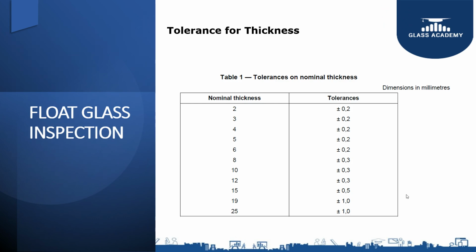So this is the general criteria for whatever thickness glasses we are producing. This is as per EN 572 Part 2 of clear soda lime silicate glass manufacturing process. For all nominal thicknesses, they have different tolerances. So in nominal, if we take 6 mm, it will be plus or minus 0.2 mm, which the EN European standard states. But our Saint-Gobain glasses will always have a tolerance of minus 0.2. We have very stringent limitations on a product so that it should not later create any issues on products or in fittings.